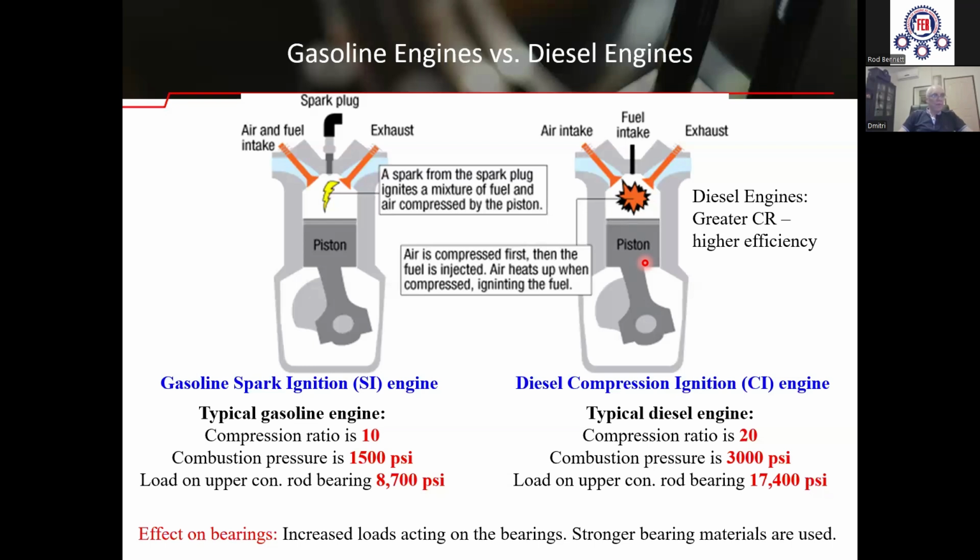The upper halves of the rod bearings working in diesel engines are made of special high-strength materials. The adverse effect of very thin minimum oil film thickness, such as frequent direct contact with the shaft and the risk of seizure, can be reduced by using anti-friction coatings.